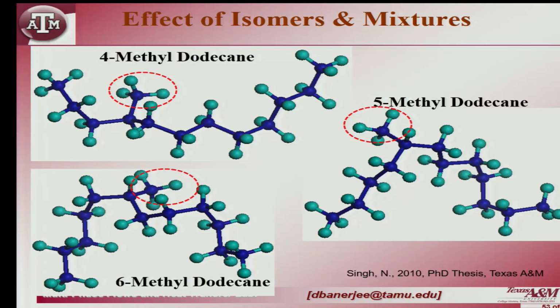Okay. So, now the interesting thing is that same chemical, if it has different chemical structure, will layer up in a different way around the nanoparticle. So, it is not only the chemical formula, but the chemical structure now becomes an important parameter. And so, Navdeep in his thesis showed that each of these different molecules, they are the same chemical formula, it is the same C16H34. Okay, but depending on whether it is a straight chain or a branch chain, or depending on how many number of branches you have, the Kapitza resistance was changing.